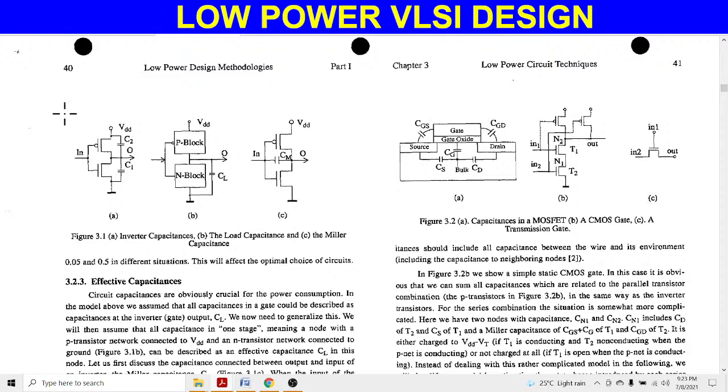When we discuss the operation of CMOS, we know that for the complete operation, first we have to provide the input as 0, and later on we have to provide the input as 1. When we provide the input value as 0 in the CMOS inverter, the PMOS acts as a short circuit and the NMOS acts as an open circuit, because the condition to operate PMOS is that when the input voltage is less than its threshold voltage, at that time it will operate.